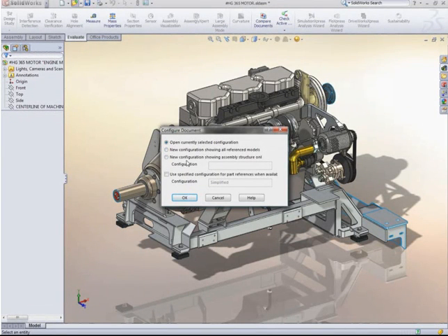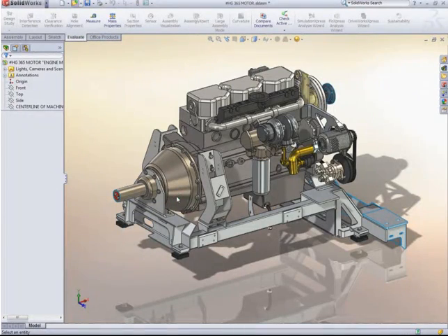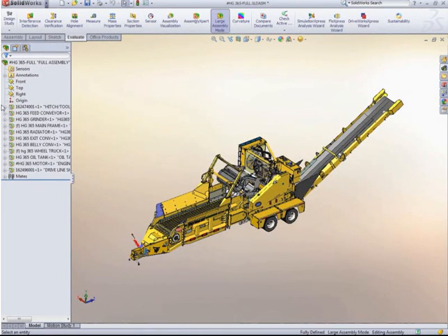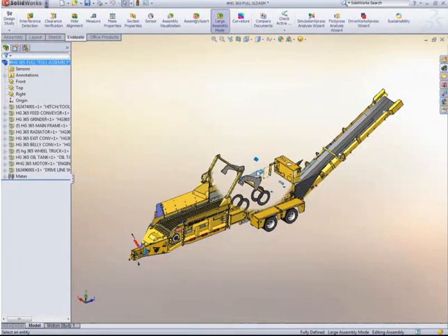This gives us many extra capabilities, like opening the entire assembly with everything suppressed, or creating a brand new configuration on the fly. Here we'll open the top-level assembly, but substitute every sub-assembly that already contains a SpeedPack configuration. Every SpeedPack sub-assembly is empty, and if we move the mouse over the main assembly, we'll see that it only contains a handful of components.